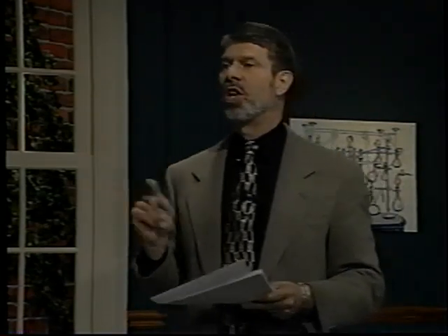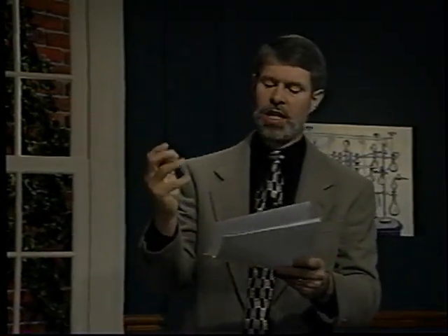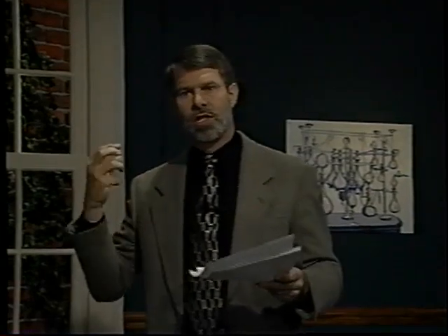The second law then is a statement of the conservation of current in an electrical circuit. It says the current flowing into any junction equals the sum of the currents flowing out of that junction. And this is pretty logical because current is just a matter of electrons flowing through the wire. So the number of electrons flowing into a junction equals the number of electrons flowing out of that junction.